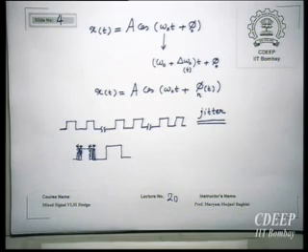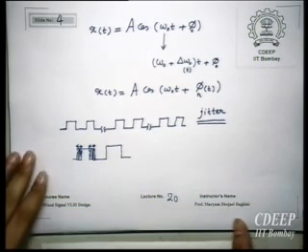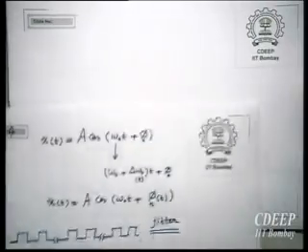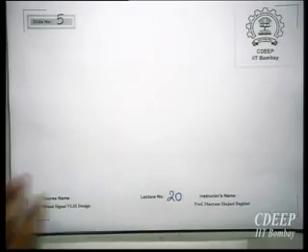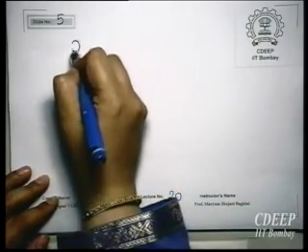So this exists in the PLL also. So the VCO has its own jitter. Even if you consider the reference signal, which is the input, doesn't have any jitter, it's ideal, the VCO has its own internal jitter because of sources of noise and temperature drift and other things. So how does the PLL respond to this jitter? What will be the effect of this jitter in a PLL? So we go with the charge pump model of the PLL and then we'll look at what will be the effect of jitter in the PLL.